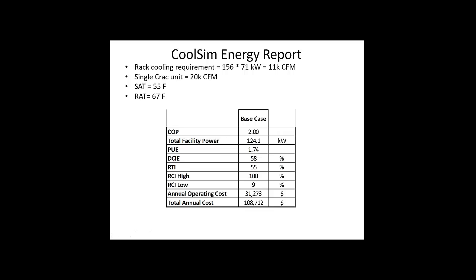Now, if we take a look at the energy report that comes out of the CoolSim system when you run a job, it shows like this. The COP here, this was an assumption. By the way, in CoolSim right now, you do have to make an assumption about the baseline COP. COP is the coefficient of performance. It's simply a ratio of the amount of energy required to reject the same amount of heat, or an amount of heat, out of the room.